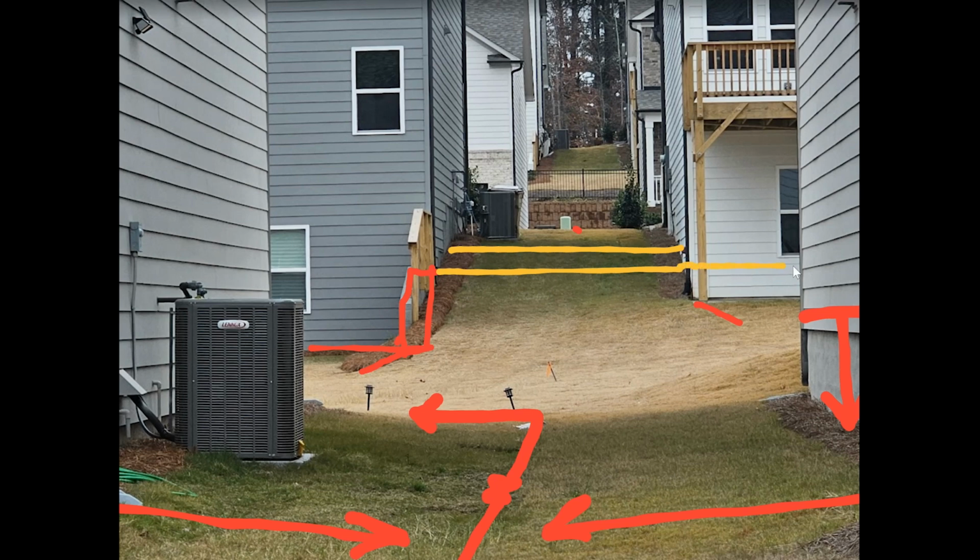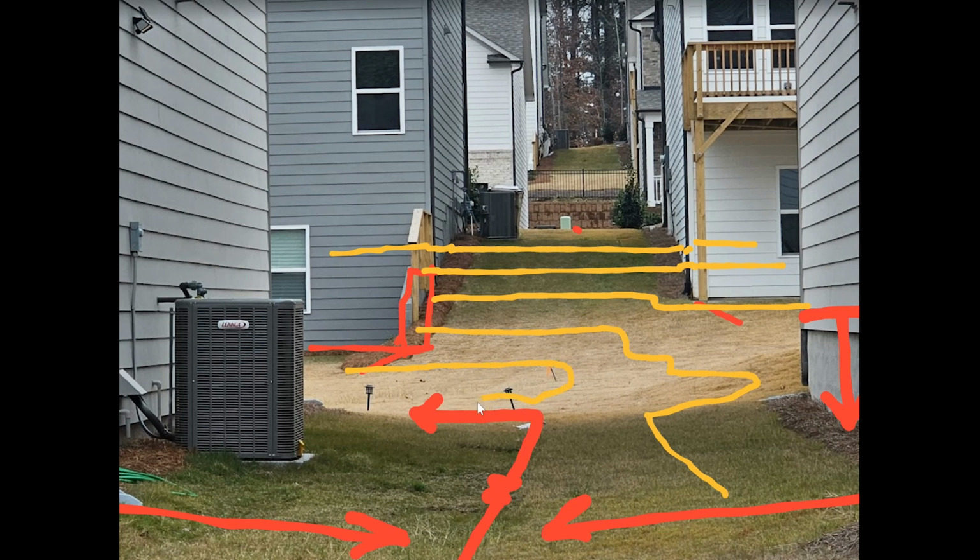And here, just giving the examples of what the contours would look like. Again, on the plan view, we won't draw the contours coming around the house. I'm just drawing that to give the example of what happens to the contours. The contours are coming off the left-hand side of the house and sort of wrapping around a hill, and then there's a ditch sort of in the back. And then that swale in between those basement lots and the houses in the foreground here. In between all that is that pretty big swale that they've created back there.